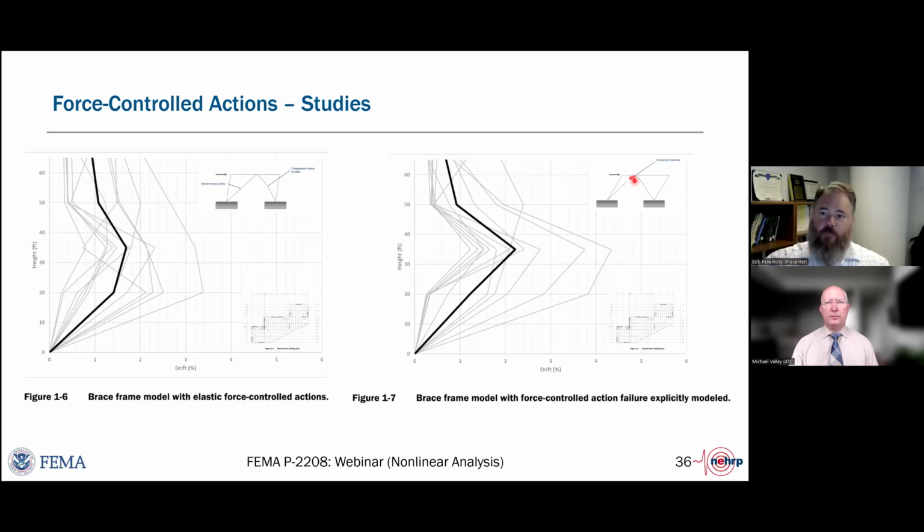It is presumed that your deformation-controlled elements have strain hardening and median properties in them, so they're producing some sort of expected demand, and then you compare that against the expected capacity for this envelope check or unacceptable response check.